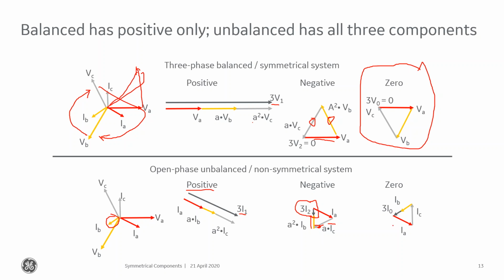The other question is, is there zero sequence current? And yes, there is. If I take A here, don't do anything to it, and take C, I'm not shifting it, I'm just going to superimpose C on the end of that. And then I'm going to superimpose B on the end of that vector. Then here is my 3I0. So once I take 1/3 of that, I do have some small quantities of zero sequence current.